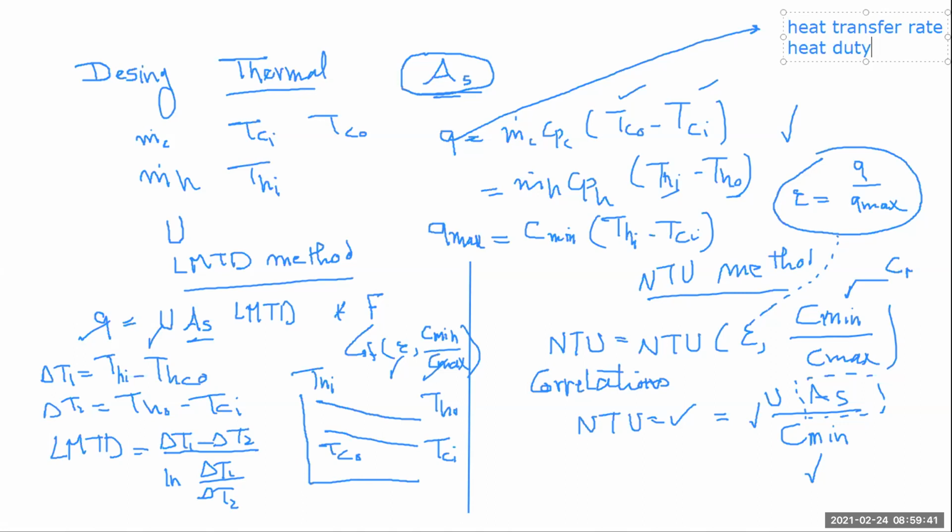But otherwise, especially with heat exchangers that have tubes that the fluid has to pass through, there is friction. Friction means we are talking about major losses. There are bends, there are valves, so there are minor losses. So you need to overcome the losses, and sometimes natural convection alone is not enough to overcome these losses, and you need to circulate the fluid by a pump. So pumps are needed? Yes, definitely they will be needed in most of the applications to make the fluids move. And accordingly, heat transfer by convection takes place.